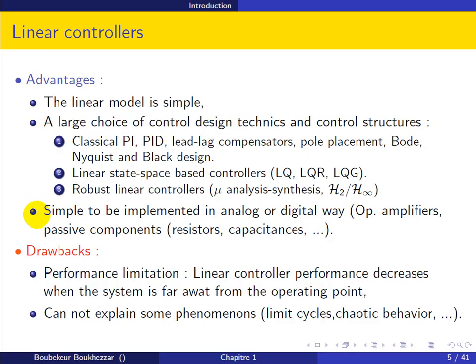So the control structures are the kind of controller, and the control design technique is the technique we use to tune these controllers. For example, we can use classical PIDs, lead lag compensators, pole placement in both transfer function and state space approaches.